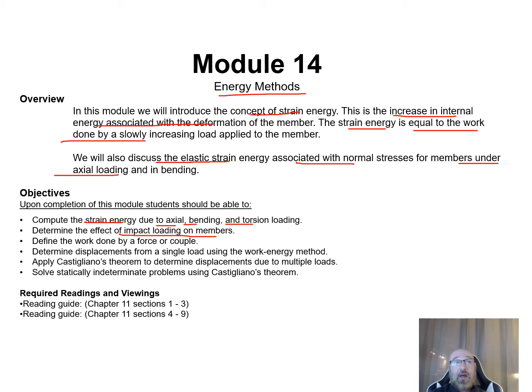Define the work done by a force or a couple. Then we're going to look at determining the displacements from a single load using the work energy method. Then we're going to apply Castigliano's theorem to determine displacements due to multiple loads, not just a single load. And last, we're going to solve statically indeterminate problems using Castigliano's theorem.